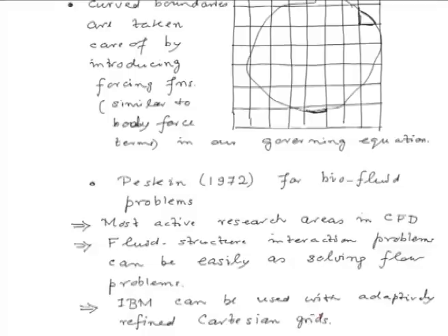Let us suppose in a specific region of the problem domain, we would like to have a very fine mesh based on some error criteria. So, we can have grids of different densities in different domains to take care of the boundaries. Maybe we can have a fairly fine grid close to the boundary, and these features are permitted in the context of the immersed boundary method.